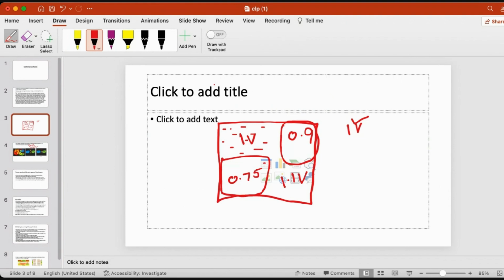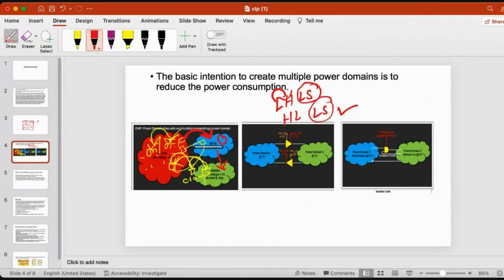It is also called daisy chain, or mother and child fashion. This way we place power switches at regular intervals in the design. When the device goes into off state, these cells stay active and supply power to the cells present in this domain. So this way we define four different cells when you are going for low power design.